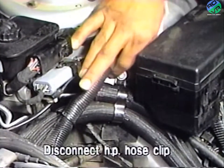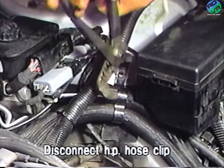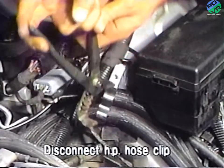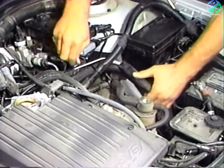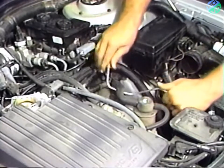After freeing the hose, remove the bolt from the brake hose attaching clip and undo the spring clip with channel lock pliers. Next, remove the high-pressure hose from the clip and pull the hose clear of any obstructions so it can be pulled out from under the vehicle.